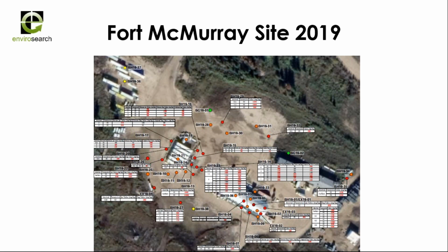And the key takeaway from having the near infrared reflectance spectroscopy available is that we are able to adapt our drilling plans and make sure we investigated every potential source of contamination and staining on the site and get a real accurate and full inventory of the contamination and liability that was present.